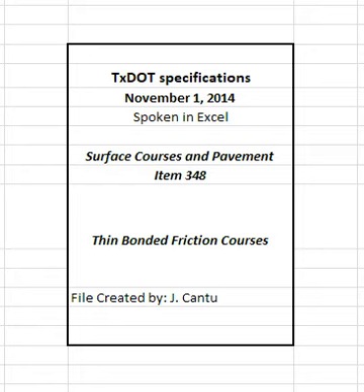4.4.2.2 Engineer's responsibilities. 4.4.2.2.1 Superpave Gyratory Compactor. The engineer will use a department SGC calibrated in accordance with Tex-241-F to mold samples for laboratory mixture design verification. For molding trial batch and production specimens, the engineer will use the contractor-provided SGC at the field laboratory or provide and use a department SGC at an alternate location. The engineer will make the contractor-provided SGC in the department field laboratory available to the contractor for molding verification samples.